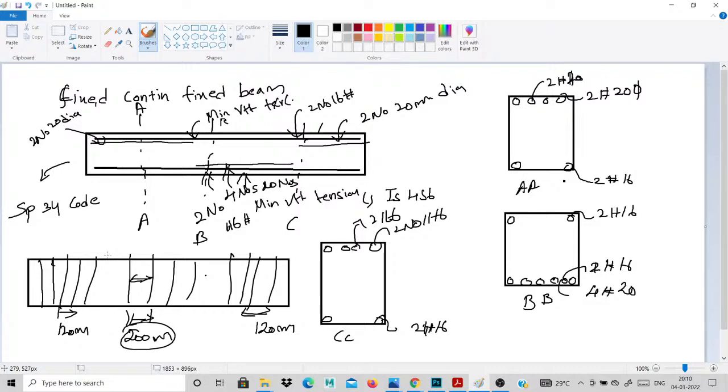The calculation is by moment distribution; all of us follow the moment distribution method. Another one is redistribution. You know redistribution; I will tell only that one concept. Redistribution is this: this is our beam, and the moment at this corner, 15% of the moment, is redistributed to the center of the beam. That is called redistribution. Redistribution is allowed for 15 to 20% for your beams.